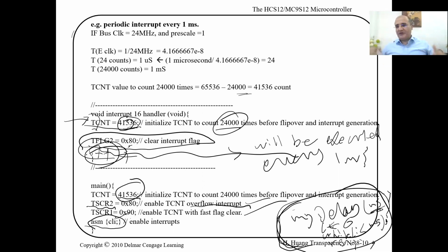If you want i to increment every 1 millisecond, you use it inside a function where you reset i to 0 and it counts. For example, you want a delay of 100 milliseconds: while i is less than 100, stay stuck in this loop. When it reaches 100, you're released.